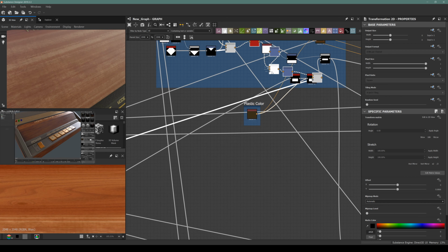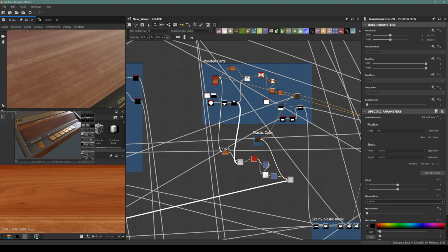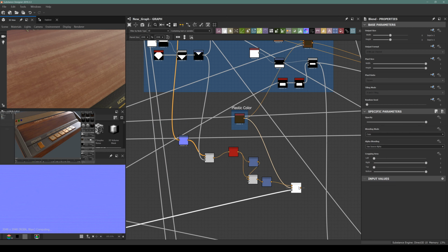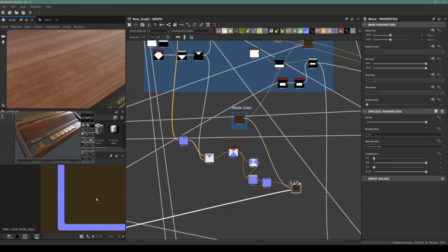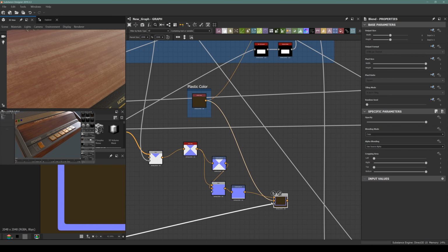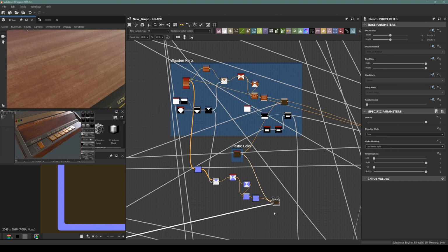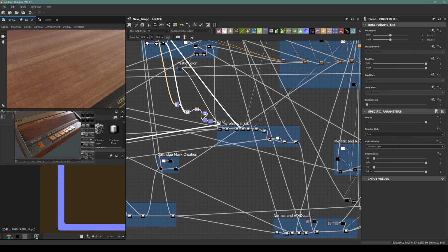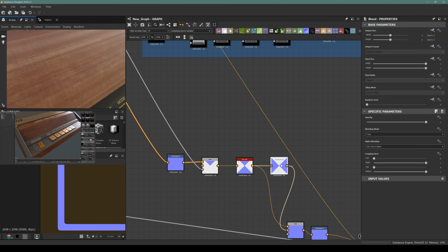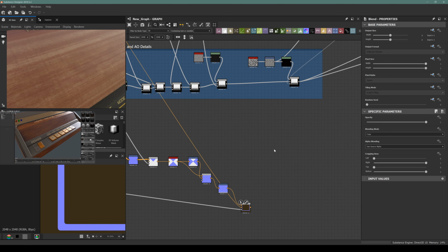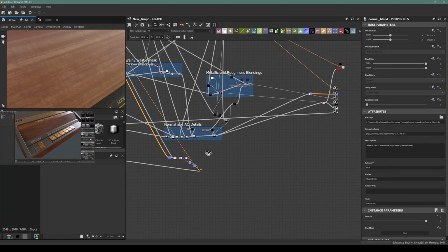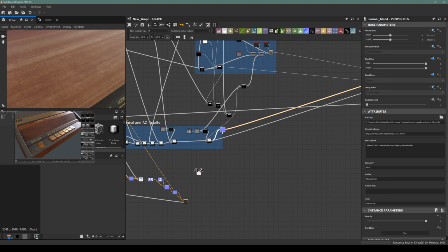This makes the rectangular conversion. We will just change this input to normal map, and at the end we will be having this over this color, but this time we will use a normal blend node with this mask for this part. Let's try it first. I will move this here. We have this normal detailing there, and we will use a normal blend node here.